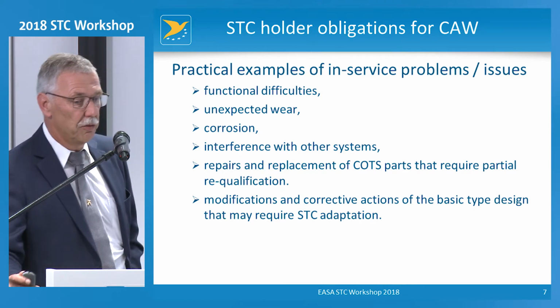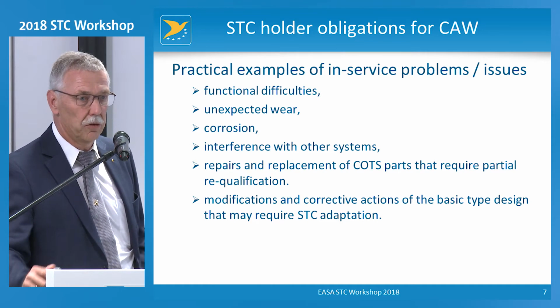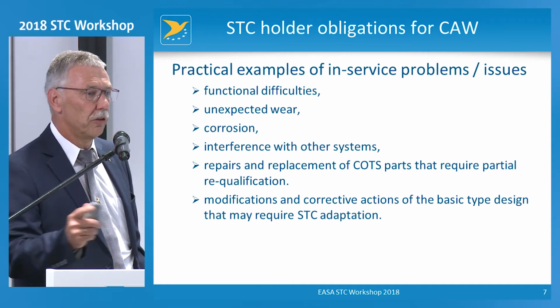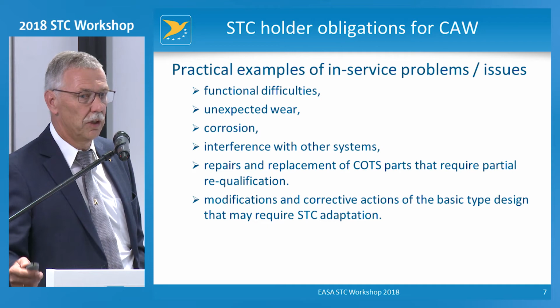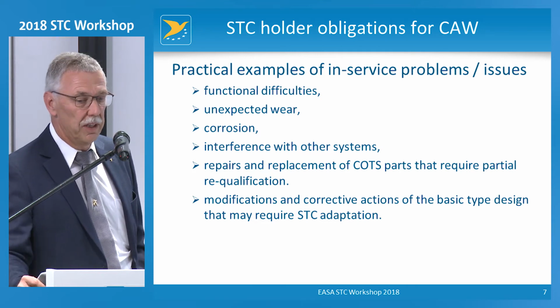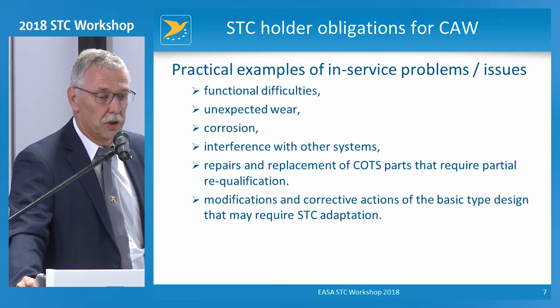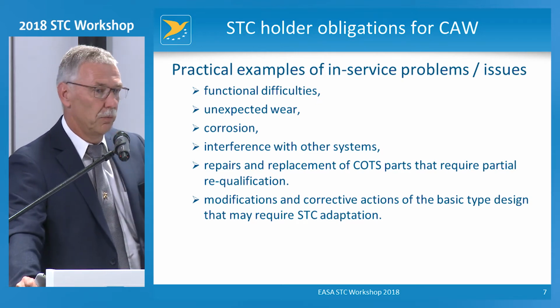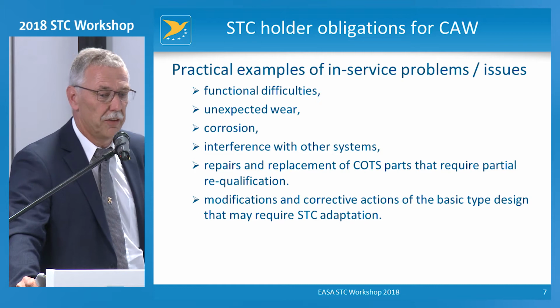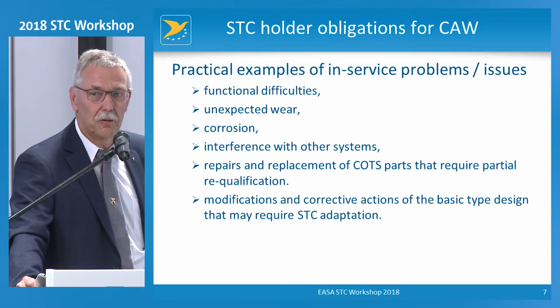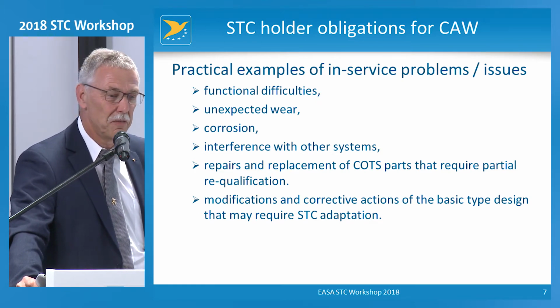Sometimes also replacement of COTS parts, commercial off-the-shelf parts that you have installed with your STC. They need to be replaced, and some customers want to buy them like a printer in MediaMarkt instead of using your qualified part or something like that. That could create in-service difficulties.